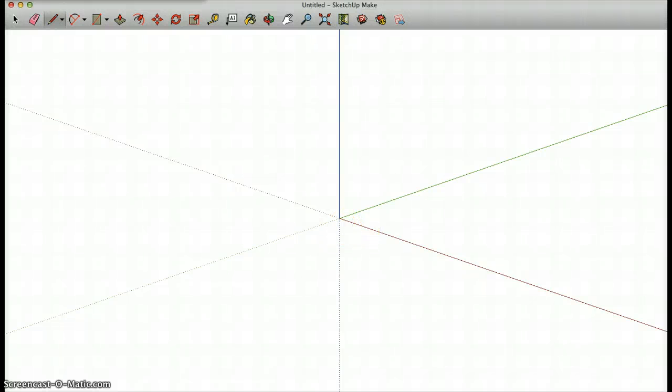I'm going to click the pencil. I'm going to click on the origin, and it should snap to the origin. Okay, it gives me that yellow circle. I'm going to click on the origin. I'm going to tell it which direction I want it to go. Hold on, I moved my thing down to where you guys can't see something that you need to see. Down here where it says length, I'm always just going to type the length that I want in that corner. Okay?